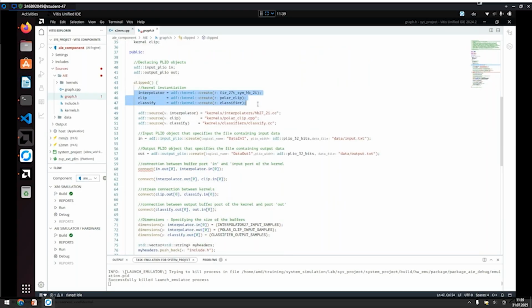These kernels would be mapped out to the particular AI engines. I don't necessarily want to show the code behind the scenes at this point, but in this case, it means that you have these three kernels being connected together in certain ways, all these connect functions. So that's the data movement description that helps you build a mesh across these AI engines. So that's really the approach that we have in there.